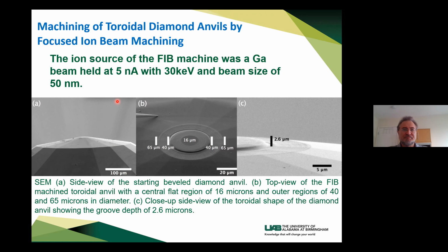Yeah, because I think the reason I wanted to point out was that if you take the density functional theory estimate for the shear modulus, the maximum shear strength for diamond at 500 GPa is around 150. But when you look at the experimental data, you see that that number is a lot higher. So that remains to be seen whether that is indeed the case for NCD anvils. Okay, Reini Bowler has a question.